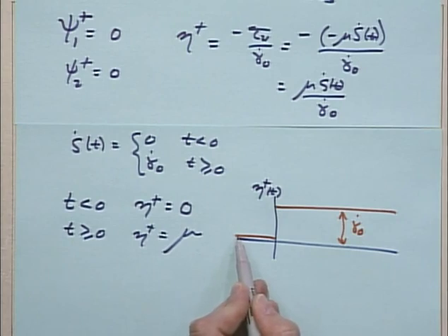If you put a Newtonian fluid into, say, a parallel plate device and don't move the top plate, but then suddenly at time t equals 0, you start moving the top plate at a steady rate, the viscosity should jump instantaneously. The measured viscosity function, eta plus, should jump instantaneously to the steady state value for all times. It's an interesting idea. Does it happen?